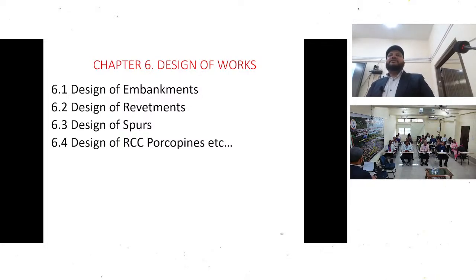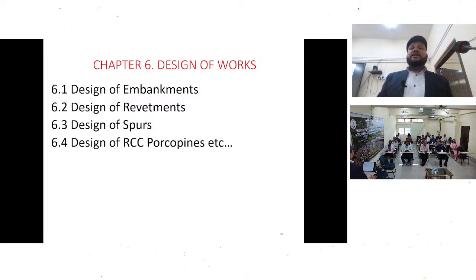And if we are constructing spurs, which kind of spurs is required, whether boulder spurs are required or whether porcupine spurs are sufficient. Then design of RCC works, and many others. Whatever kind of project we are constructing, we have to design accordingly.